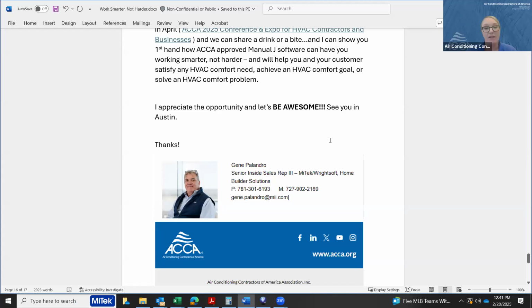Kenzie, I'm done. Thanks, Jean. I appreciate it. It doesn't look like there were any questions submitted from the group for the Q&A, but it does look like a few people had a comment about duct tape. Vincent said he doesn't use duct tape since it usually delaminates over time, but the right mastic tape or black tape with the right UL approvals is appropriate. And then David also commented saying that cloth duct tape is not UL 181 approved, but is a generic term of duct tape. As long as it is UL 181 approved and or duct mastic will seal the duct for leakage. Is there anything you wanted to add to that?